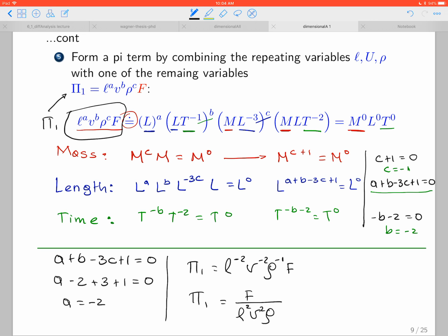But if we know that the term in the denominator, if we divide it by 1/2, it is going to be the dynamic pressure. So that's why we usually add it. It won't change the variable. And remember that the relationship that we are going to find is a functional relationship. We actually have to do it experimentally. So dimensional analysis is not going to give us that function.